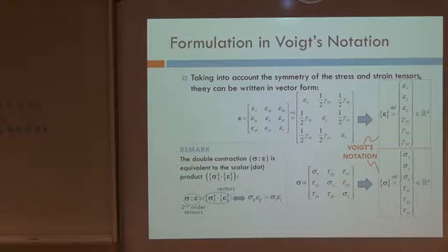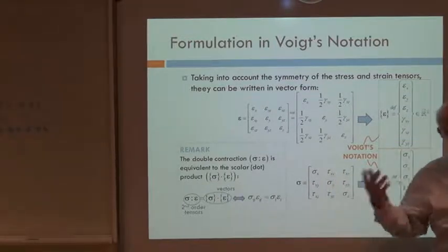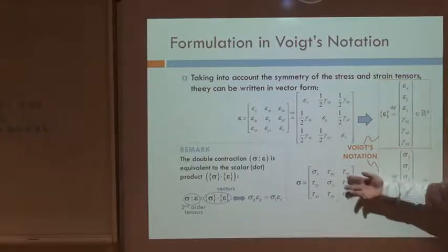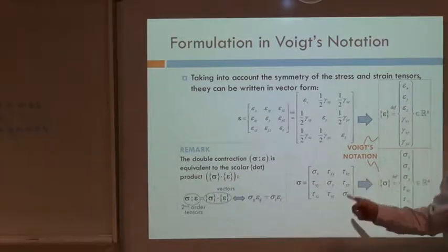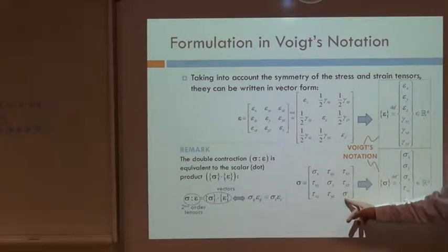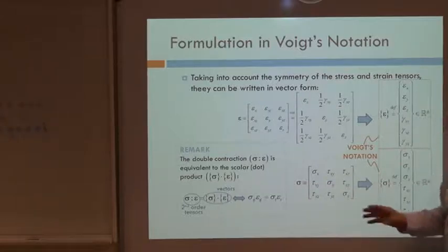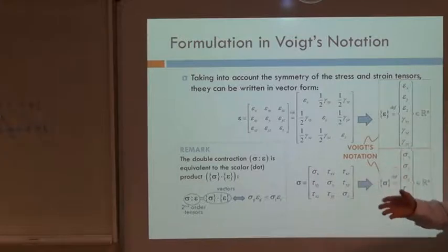About the stresses, the stress is the same. It's the Cauchy stresses, the true stresses, or whatever you want to call them, then is a second-order symmetric tensor. By the way, there are other stresses which are not symmetric. Maybe you know them, but other stresses that are used in other contexts, Piola, Kirchhoff stresses, and so on, are not necessarily symmetric. But the Cauchy stresses, which are those, are symmetric.